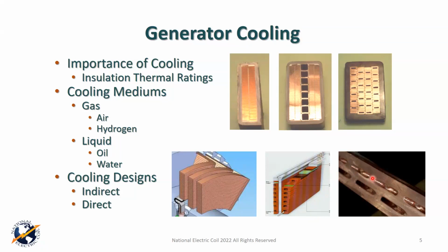And one side of these cooling vents is angled in one direction, and the other side is angled in another direction, and it makes for an extremely efficient cooling of the copper conductor in the rotor. But it also makes for a very complicated manufacturing scenario and maintenance scenario, and it's not something that some people are familiar with. It's really a challenge.